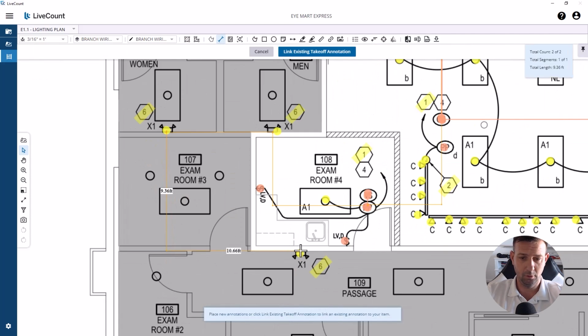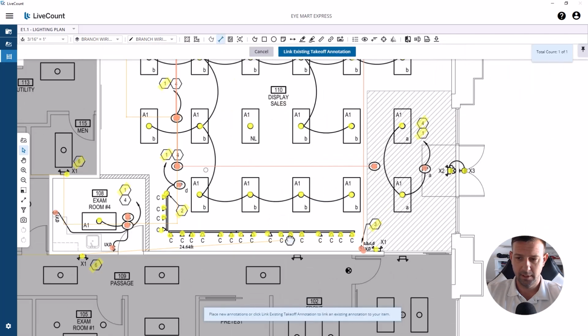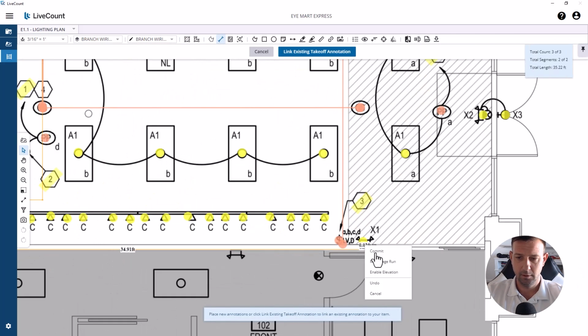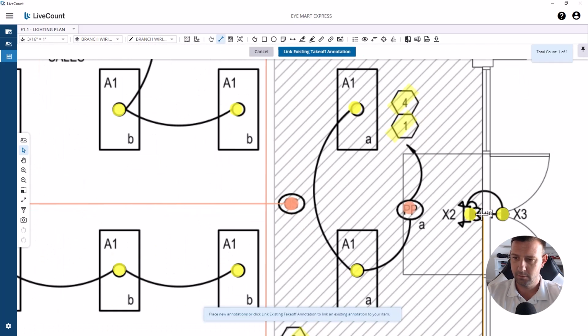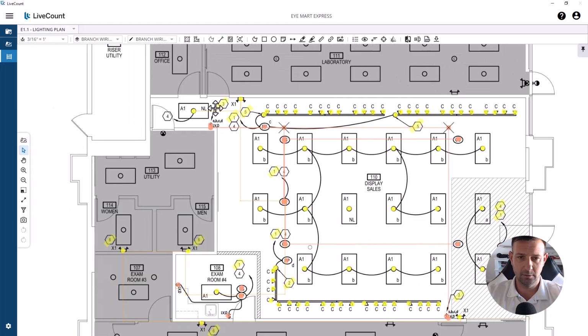May be able to pull power closer than the areas that I'm showing, but if we have enough cable to cover whatever we need to cover, it's going to be better than not. So looks like we got all of the power ran between the fixtures. Remote lighting. Now I'm going to do switch legs.